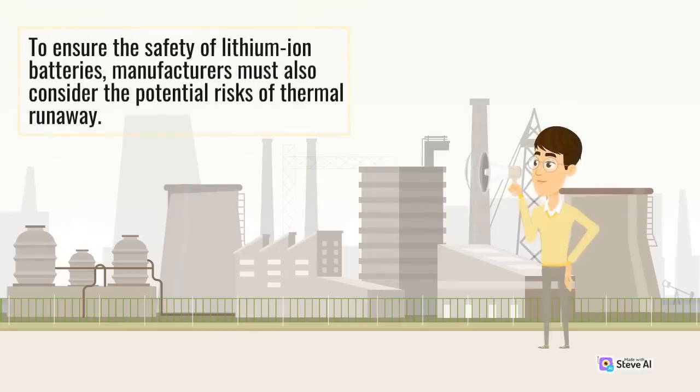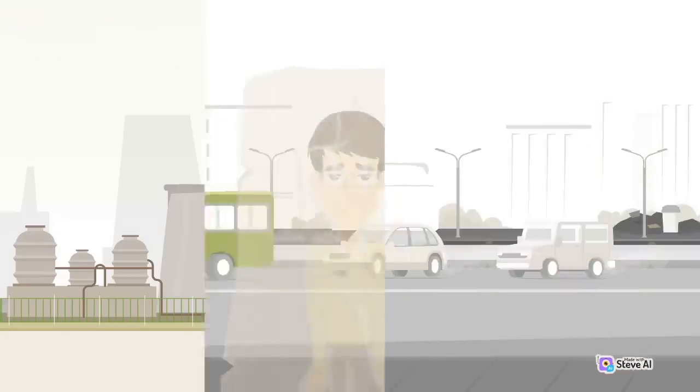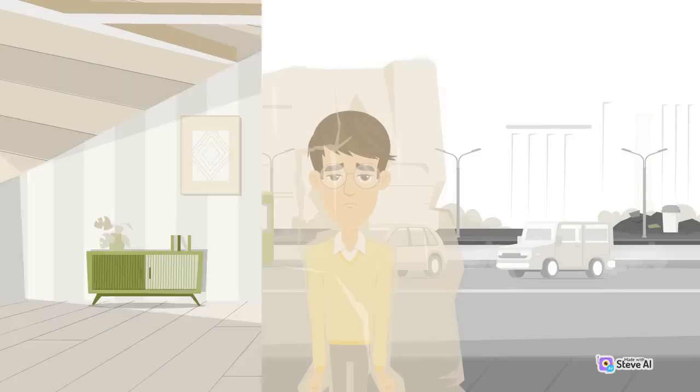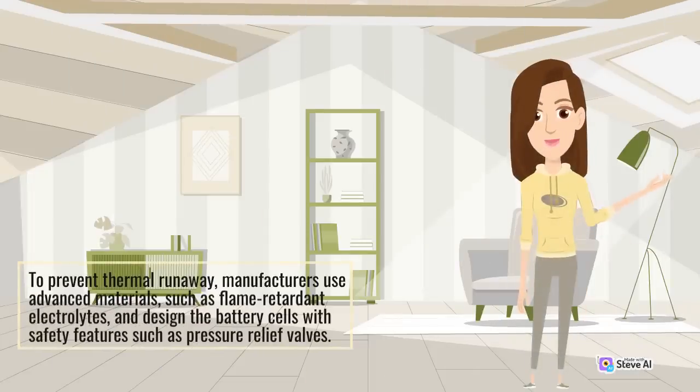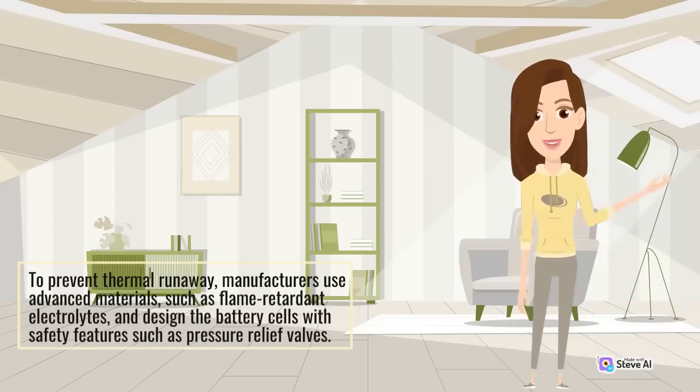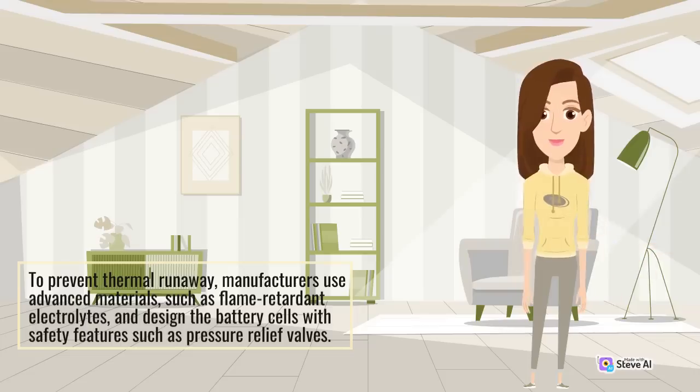To ensure the safety of lithium-ion batteries, manufacturers must also consider the potential risks of thermal runaway. Thermal runaway can occur when a battery cell overheats, causing a chemical reaction that generates more heat and can lead to a fire or explosion. To prevent thermal runaway, manufacturers use advanced materials, such as flame-retardant electrolytes, and design the battery cells with safety features such as pressure relief valves.